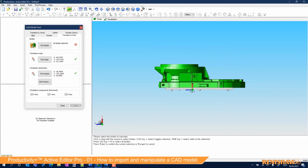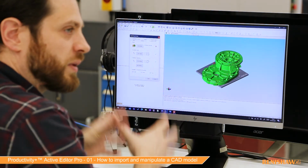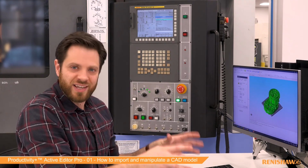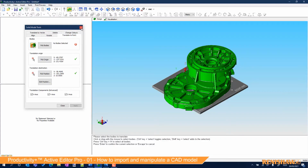So if I go back to our isometric view, now the final thing we want to do is make sure that the part is in the right location with regards to the work coordinate system. I will tackle setting work coordinate systems in another video, but actually moving these parts is a nice final step for what we're looking at today. So in order to do that, I want to select everything we've got in this view because we're going to move absolutely everything.